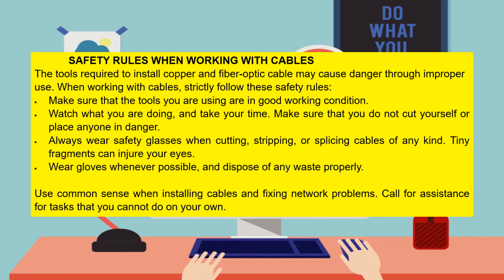Always wear safety glasses when cutting, stripping, or splicing cables of any kind. Tiny fragments can injure your eyes. Wear gloves whenever possible. Dispose of any waste properly. Use common sense when installing cables and fixing network problems. Call for assistance for the tasks that you can't do on your own.